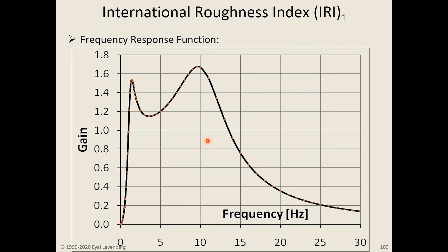To give one example, if an airport runway must be assessed for roughness, then the IRI index may be of little relevance because it cannot really see long waves, what is shown here as short or small frequencies, because large aircraft are sensitive to long waves and the IRI is incapable of measuring them. Then the right quality is not well captured with an IRI index.